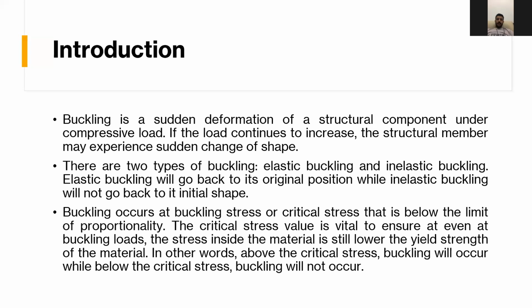The critical stress value is vital to ensure that even at buckling loads, the stress inside the material is still lower than the yield strength of the material. In other words, above the critical stress, buckling will occur, while below the critical stress, buckling will not occur.